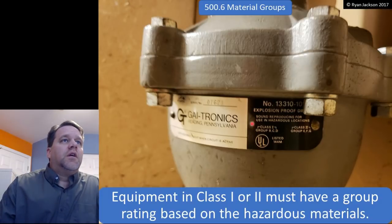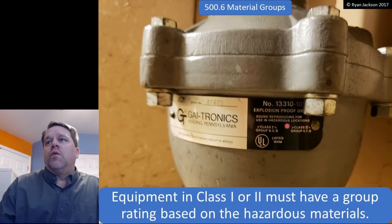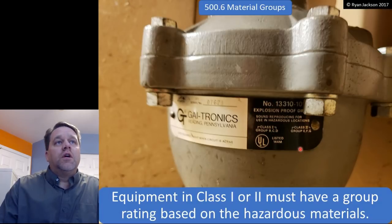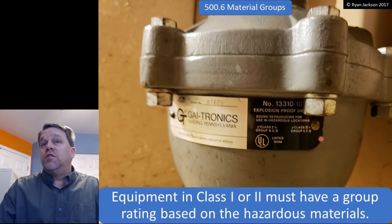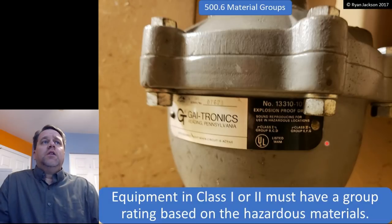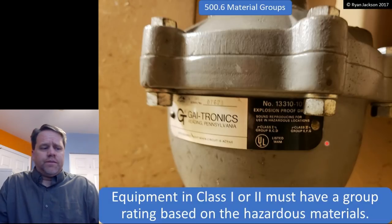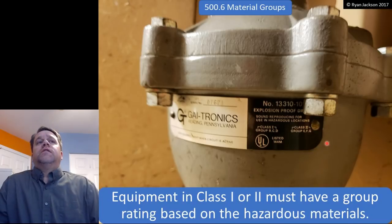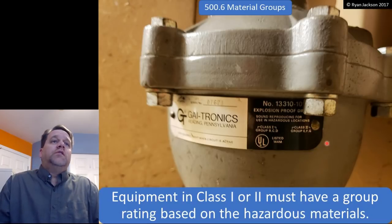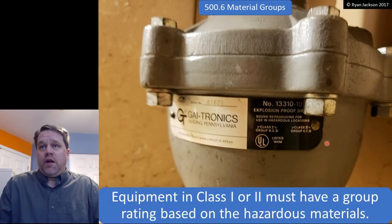Take a look at the piece of equipment here, and it says Class 1 groups B, C, or D. Cool, so we can use it in B, C, and D, and then for Class 2, we can use it in groups E, F, or G. So it's not enough to know that you're in a Class 1 location. It's not enough to know that you're in a Class 1 Division 1 or Division 2 location. You also need to know which group you're in.